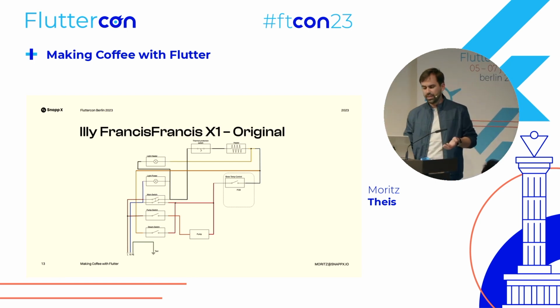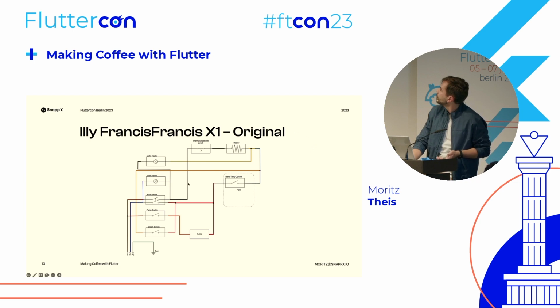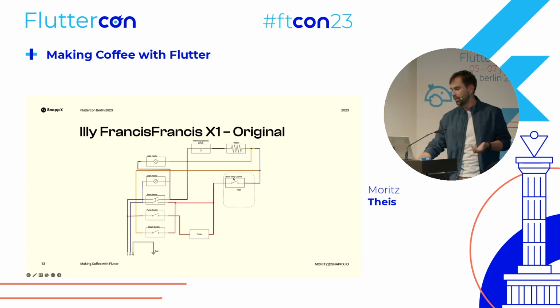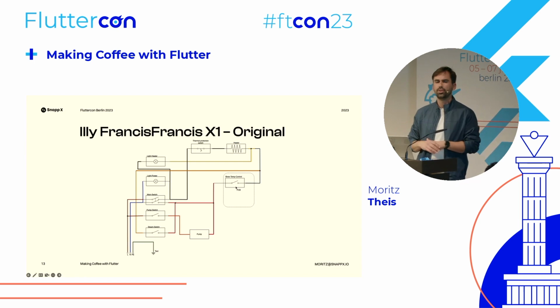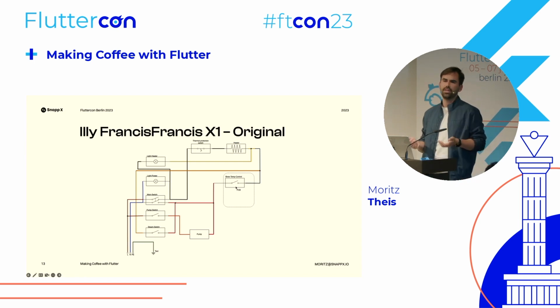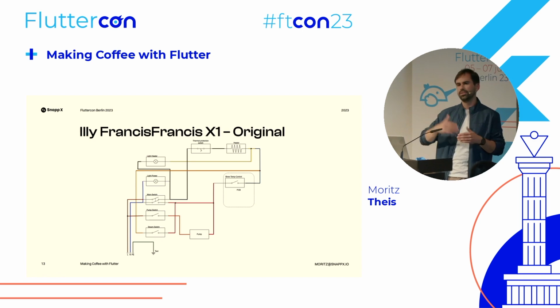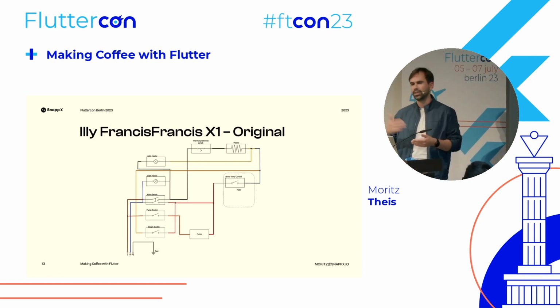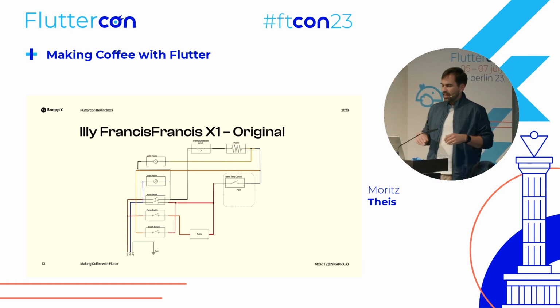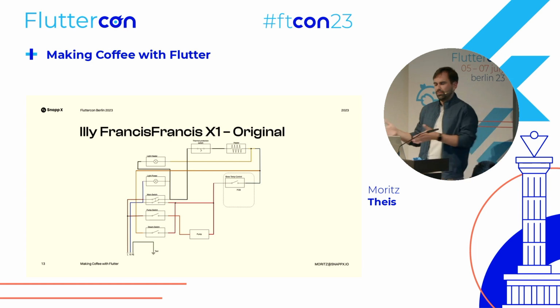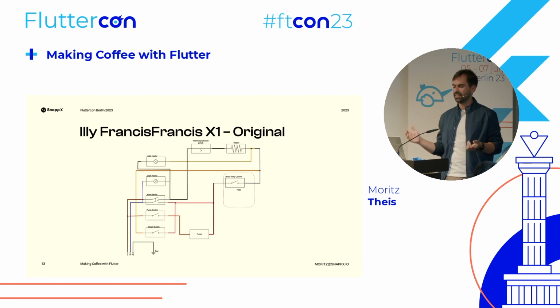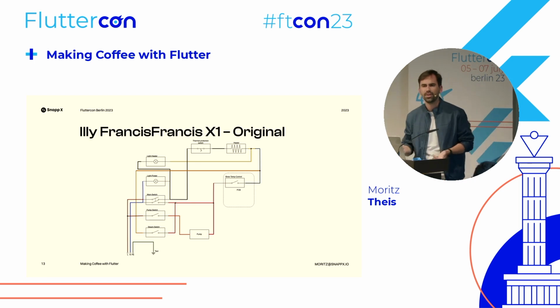Great. We have the heater, and normally the heater will be supplied by current as long as this PCB that was in the machine is saying, hey, temperature is not high enough. So there's basically a temperature sensor on the PCB looking: temperature too low, yes, heat; temperature high enough, cut off. This, as you can imagine, was an old machine, and there was nothing digital on there. And at some point, this thing broke.